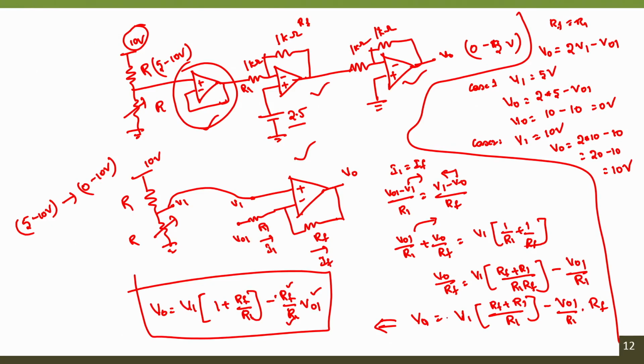No, of course, if you want to reduce the gain, at the output stage you can have an attenuator with a gain of 1 by 2, 0.5, so that the 10 volts into 0.5 will become 5, right. So, you can remove the offset, or if you properly choose the values of RF and R1 such that an input voltage of 10 volts gives an output of 5, we can even solve that problem too, right. So, this is another approach.